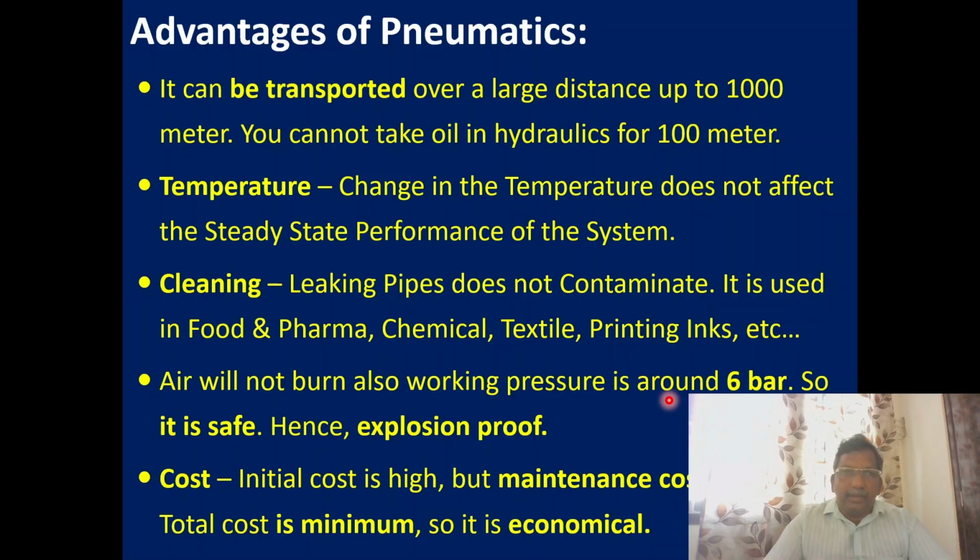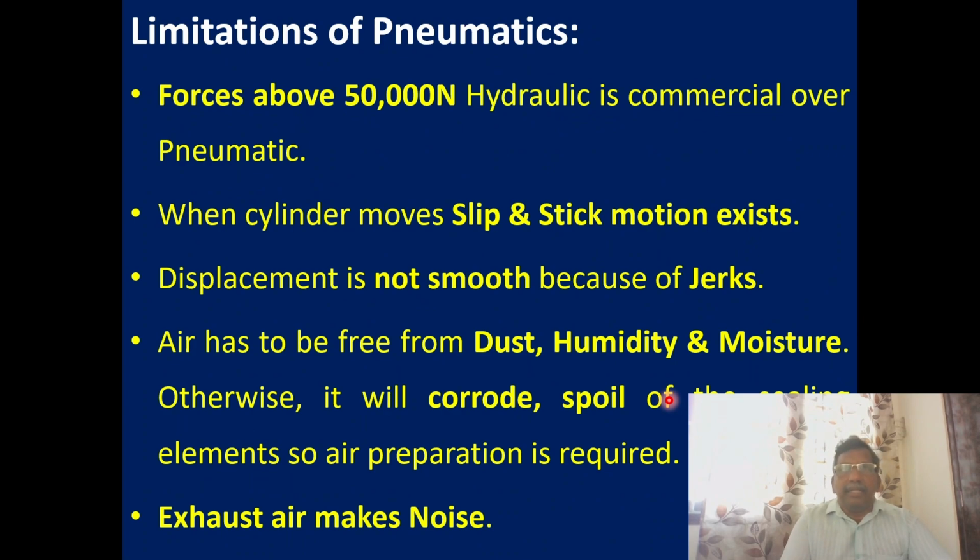The initial cost is high to install this setup, but the maintenance cost is low, so it is economical. These are all the advantages of the pneumatic system. At the same time, we have some disadvantages and limitations also. Beyond 50,000 Newton, we can't go for pneumatic. It's not commercially good, so we can go for hydraulic over pneumatic.